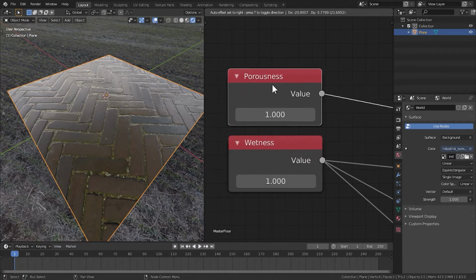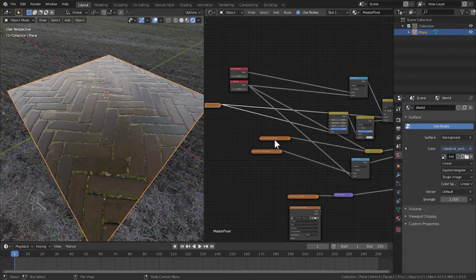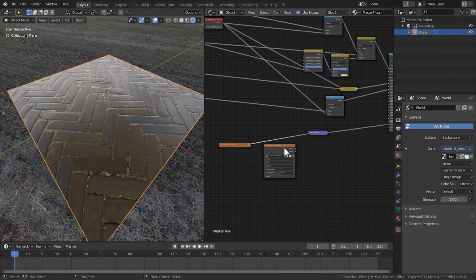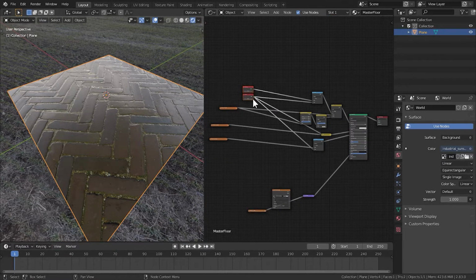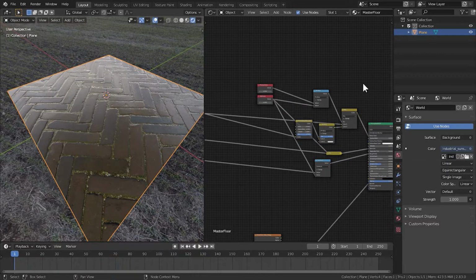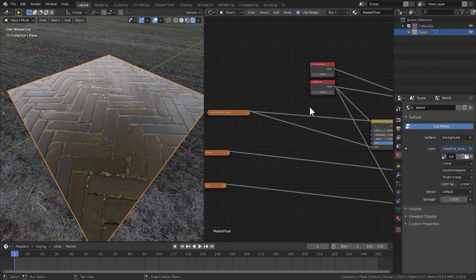So this is working. Now what I'm going to do is move all of these nodes into a custom node. So let me move them over here. So this is all of the nodes that we have. Before moving these nodes into a custom node, I'm going to press shift and right click and then drag over here so that these two pins are connected into a single pin.